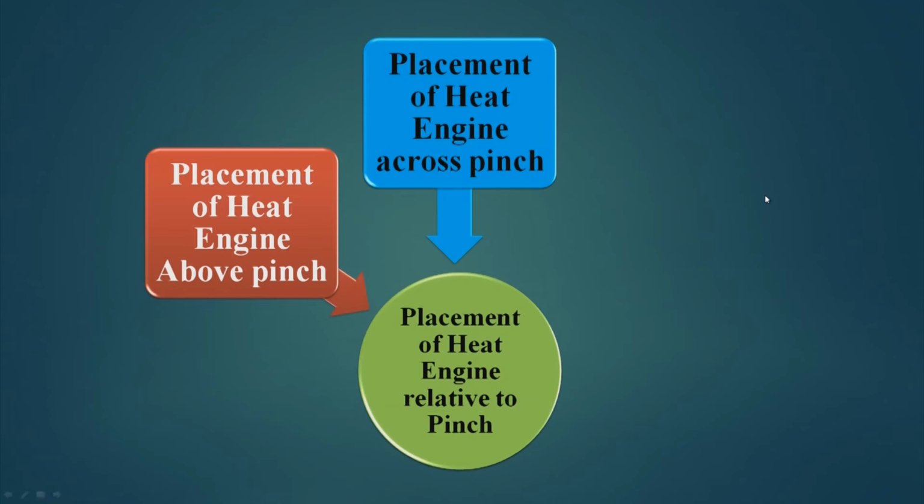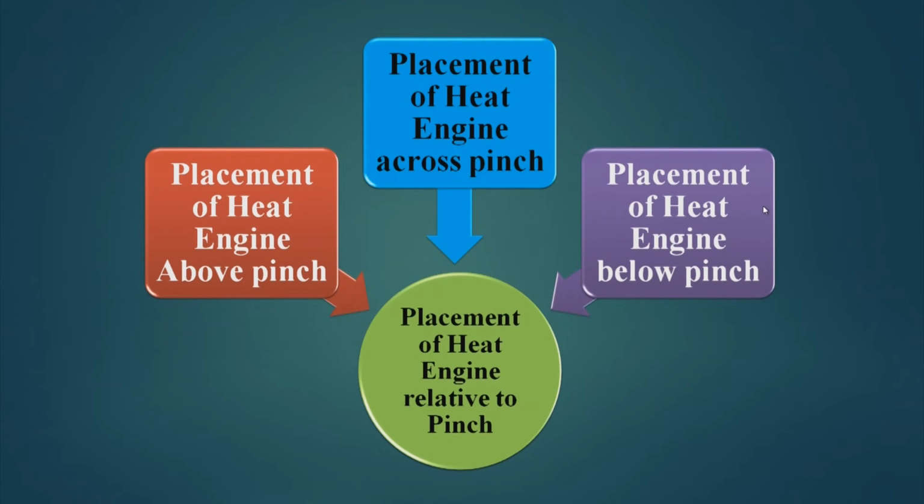Now, when I talk of placement of the heat engine, obviously placement can be done in 3 places of a GCC: above the pinch, below the pinch, and across the pinch. There are only 3 possible placements, and all these 3 possible placements we will see and check where it is profitable to place the heat engine.